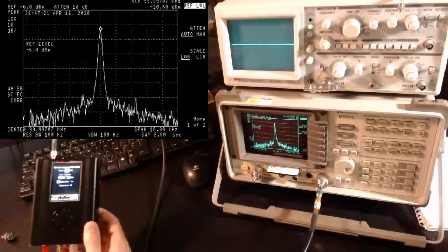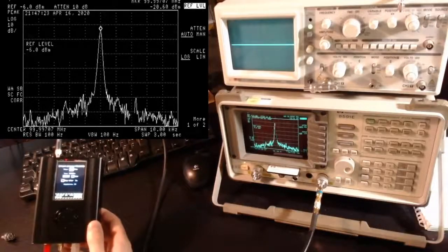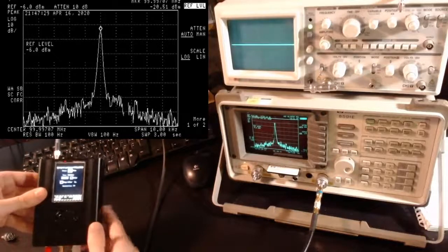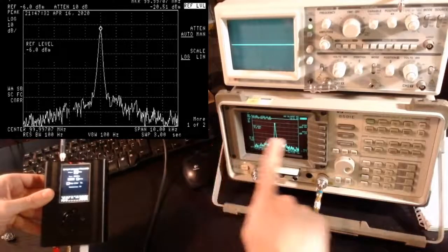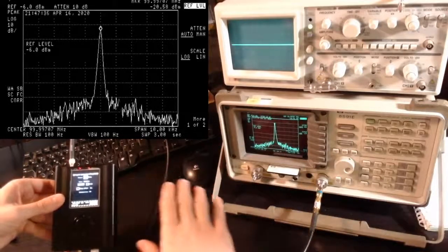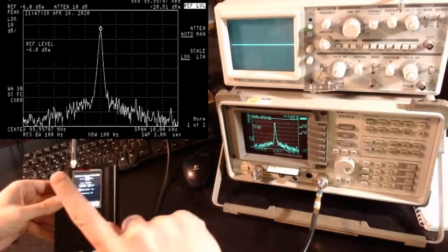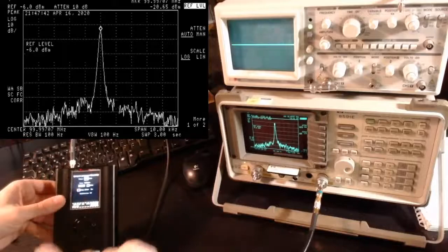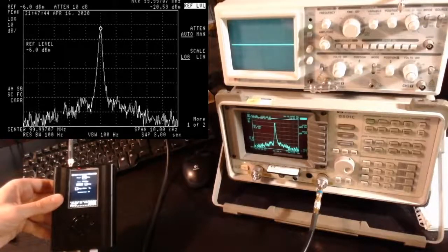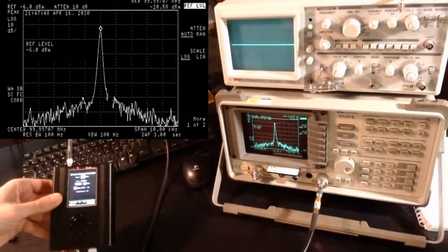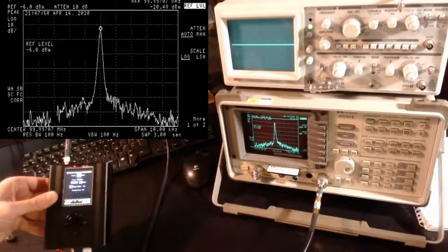It's 300 hertz lower than that, so it's actually 9.999707 megahertz, so it's basically this center frequency that we see at the moment divided by 10. So of course, when we move to 100 megahertz, the error is multiplied by 10. But that's okay. It's expected.